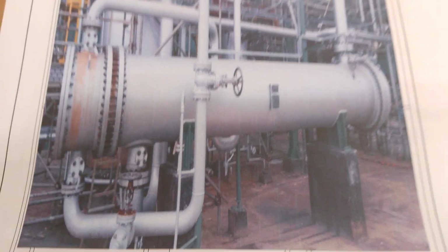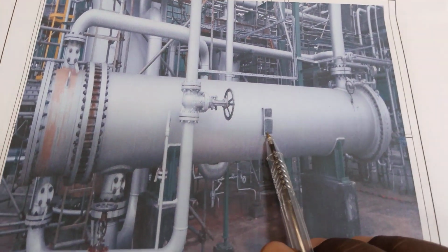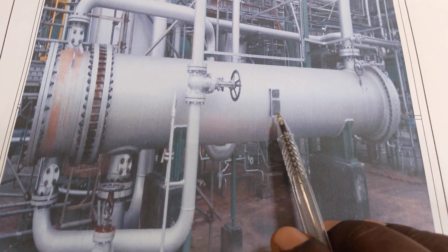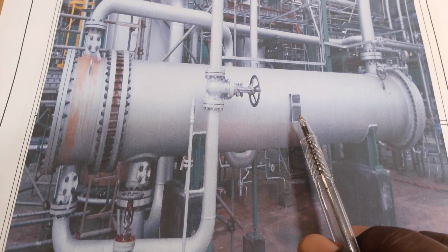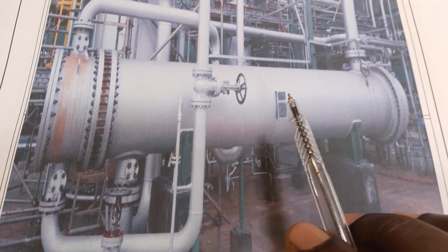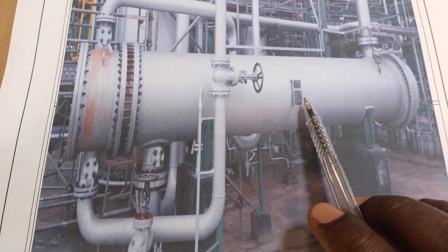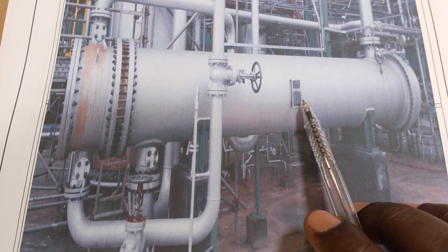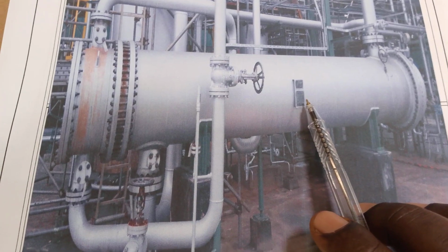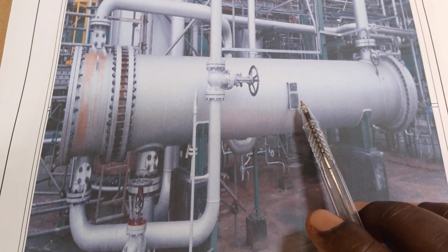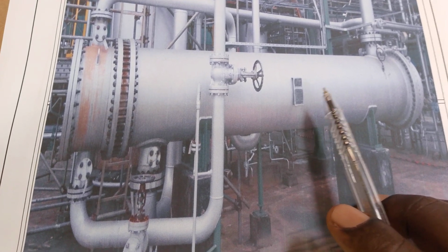As you can take a look at this equipment, this is a typical example of a heat exchanger. This is the nameplate. I've taught you some things about nameplates, but keep following me. I will teach you more about the nameplate of a heat exchanger. Through the aid of this nameplate, you can perform a hydro test on the heat exchanger, and with the aid of this nameplate, you can know the test pressure and your design pressure using the ASME Section 8 Division 1 code.